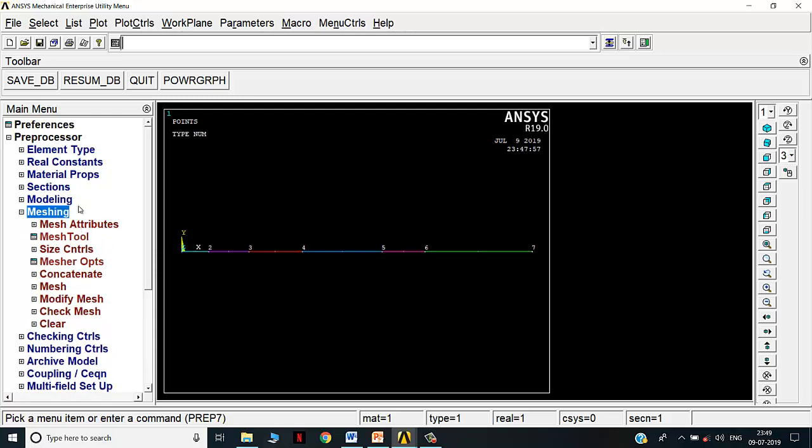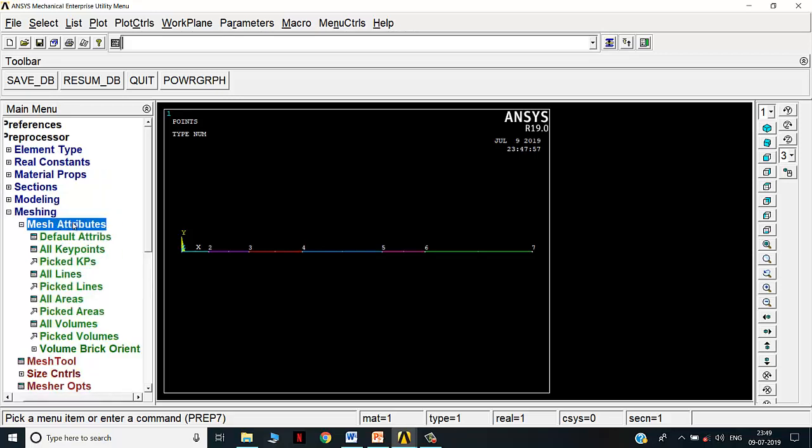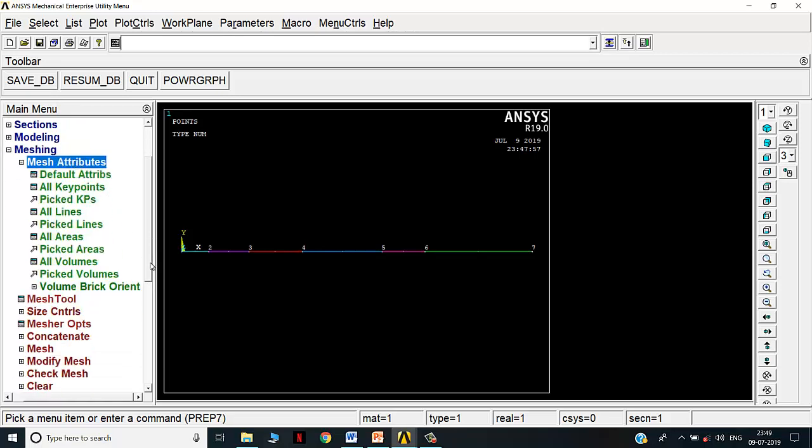As I told you, ANSYS follows a top to bottom approach. So you can find that with each and everything that I have done, I click this one, then I come to this one, this one, this one, and here I am at meshing. So you don't need to skip anything. You can come one by one. Of course, there are certain things you need not use. Like in this case, I have not used real constants because real constants are specific to some problems. Not all problems need real constants, but pretty much you follow the top to bottom menu system.